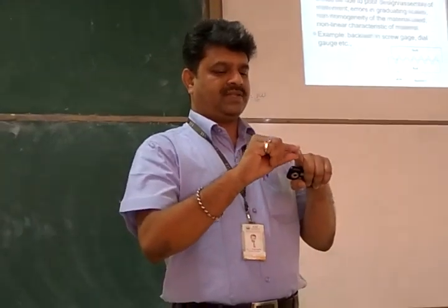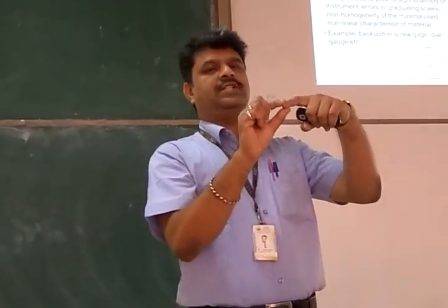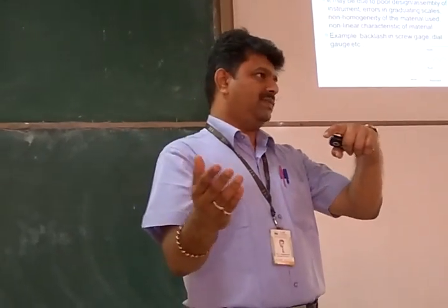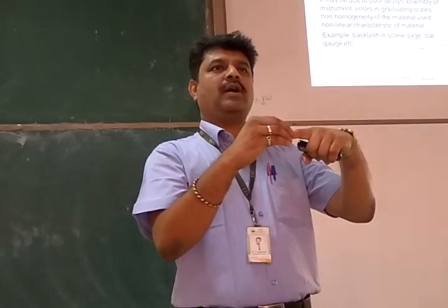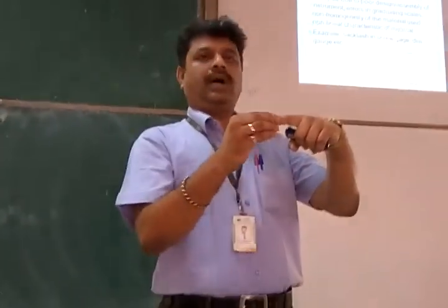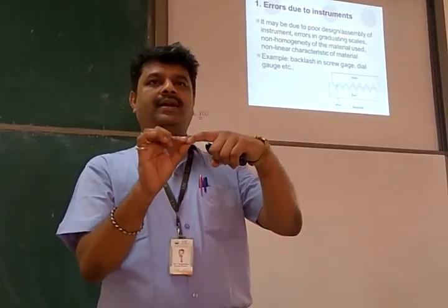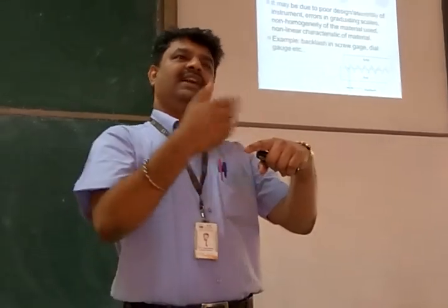So let's say because of temperature, the 2 strips of metal will bend, and the bending is proportional to the temperature. That's the working principle of certain temperature measuring devices. And in that, if the material composition is not uniform, you expect the metal strip to bend to a certain angle, but actually it will bend to a different angle.